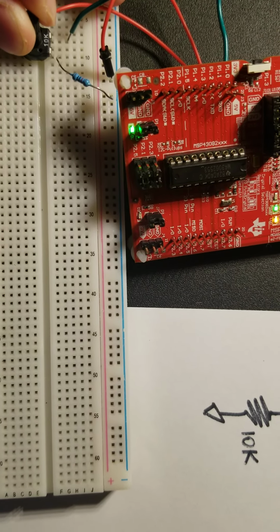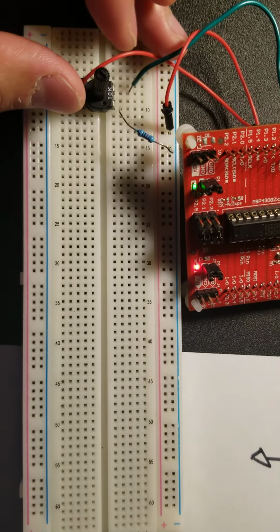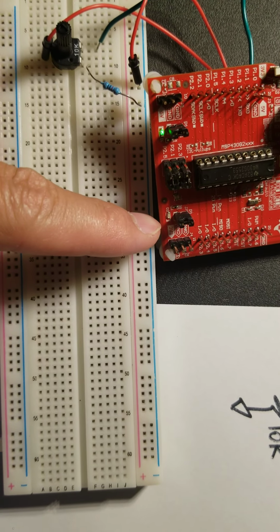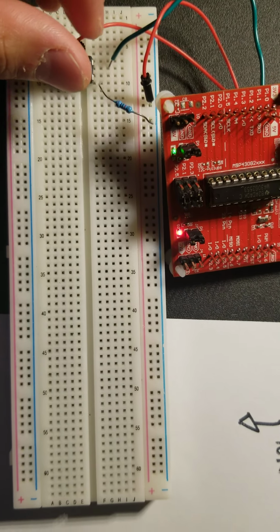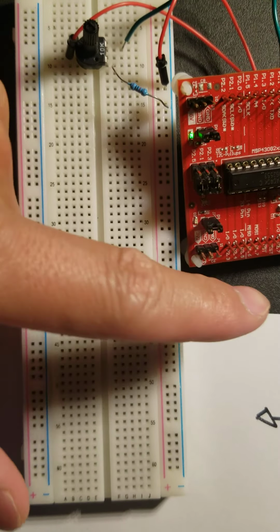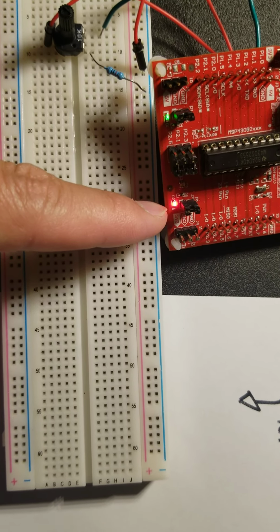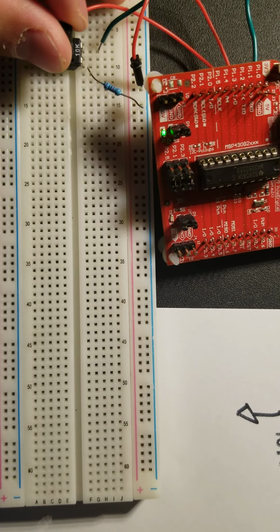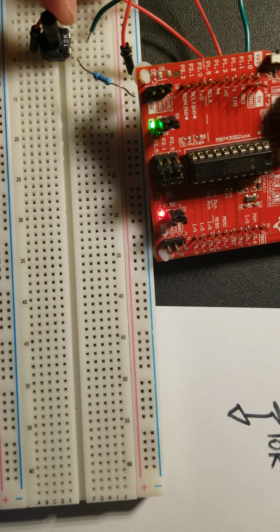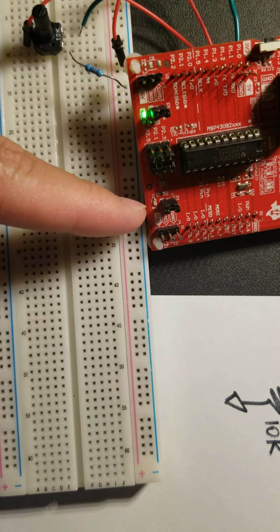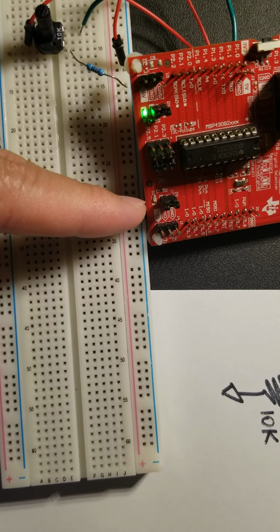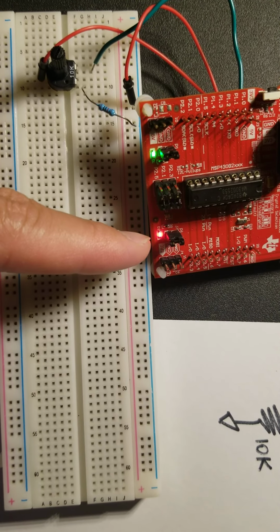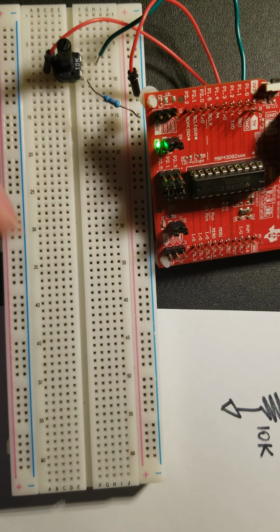The reason is in the code, I set up the voltage reading directly as a time delay between the on and off of the red LED. So when the voltage reading is larger, it takes a longer delay to turn on and off this LED, so the frequency is actually lower. So that's the lowest. If it's 511 milliseconds, then one cycle of on and off is going to take 1 second, right? So it's actually 1 hertz.